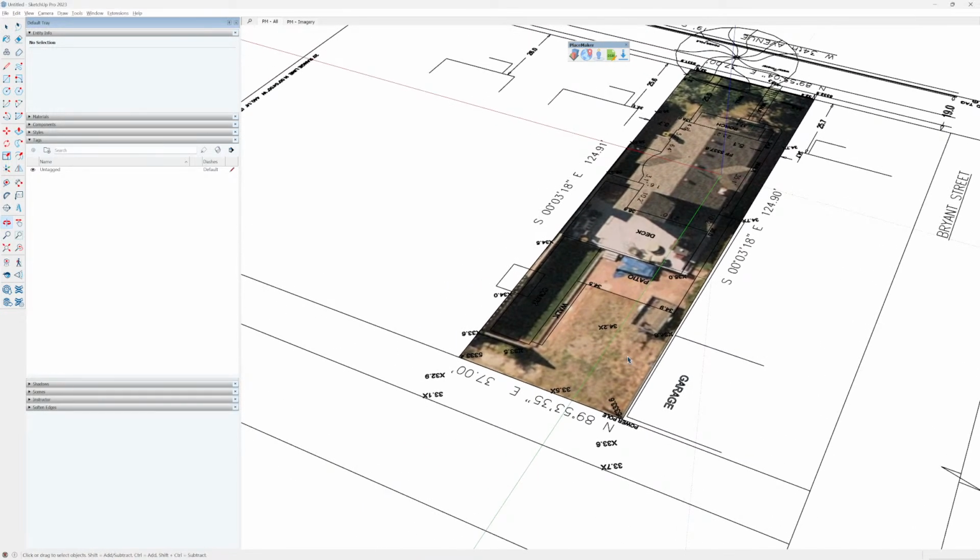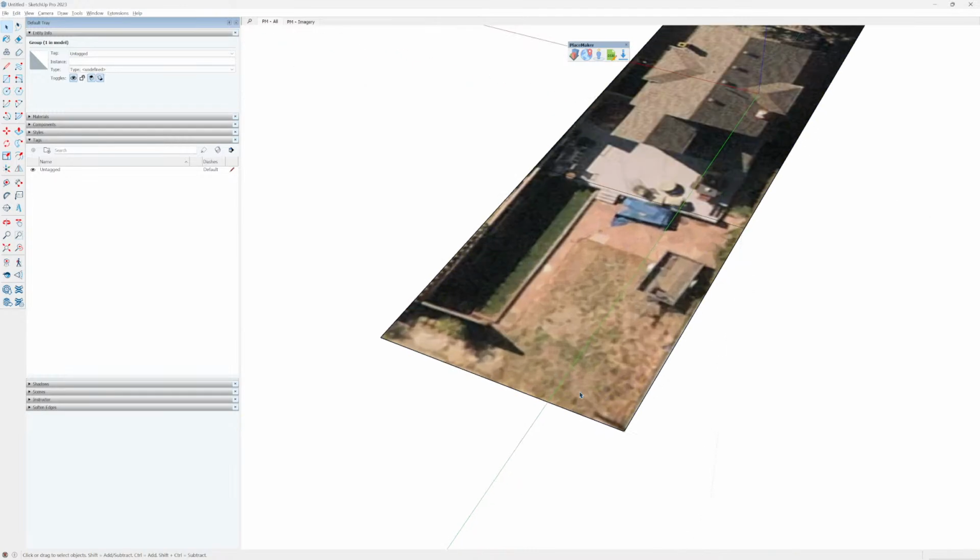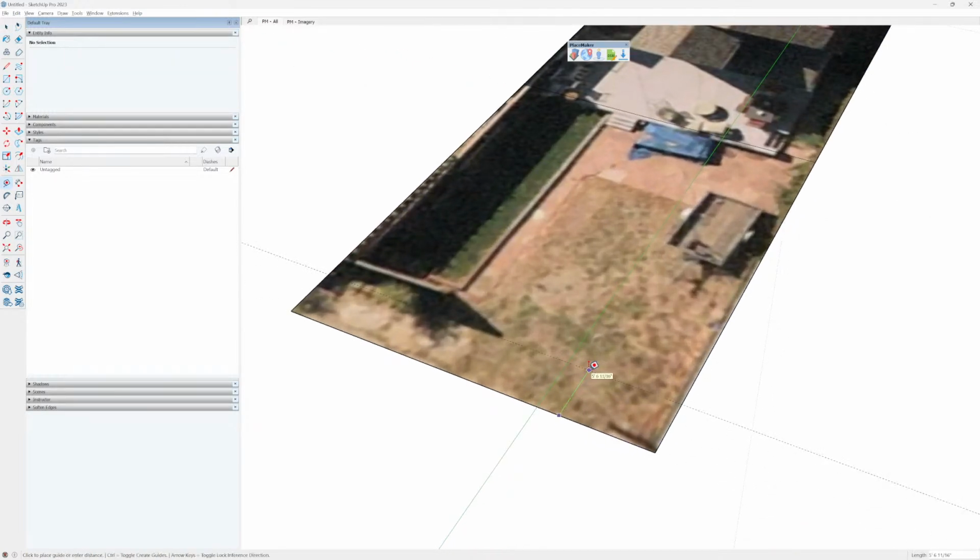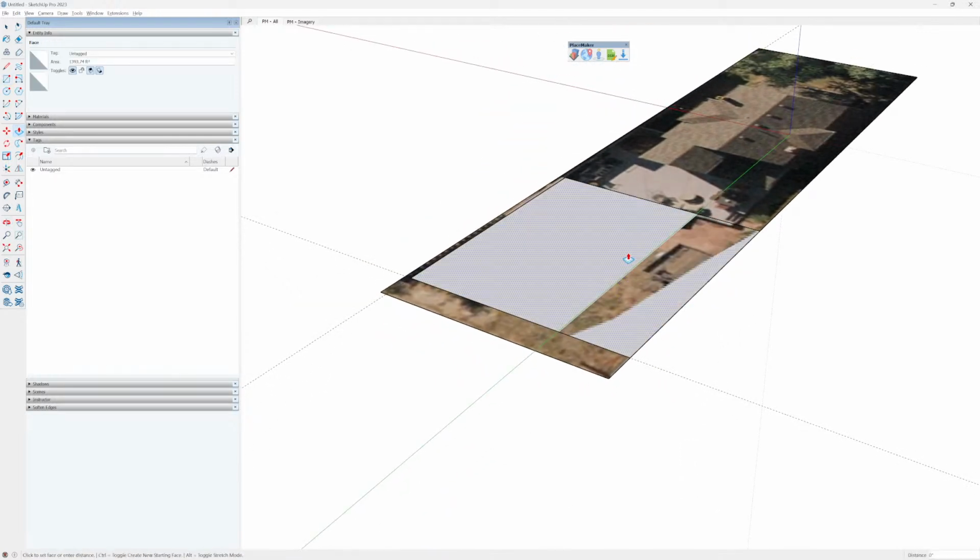We got that set up, and then I'm gonna hide this for now, and we'll set up a 5-foot setback off the rear, and then technically, we're going to leave it at 0, but we'll model the actual rules. So it'll be 0 there and then 36 feet here. So technically, I could run the building 36 feet along the back, which just isn't going to happen. So anyways, let's draw a rectangle here, and we'll go over to there. So that's the footprint of where we're allowed to build.